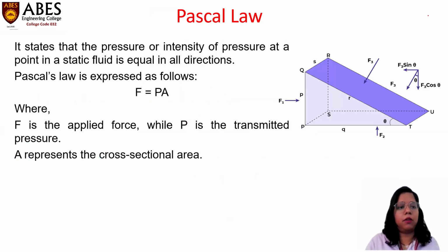What is Pascal's law? Pascal's law states that the pressure or intensity of pressure at a point in a static fluid is equal in all directions. We can also say, according to Pascal's law, the external static pressure applied on a confined liquid is distributed or transmitted evenly throughout the liquid in all the directions.